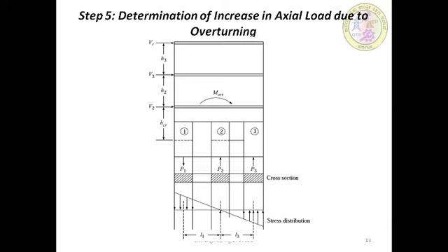Then in addition to these forces, sometimes the lateral forces from winds or earthquakes create a severe overturning on the building. If the overturning moment is great enough, it will overcome the dead weight of the structure and cause tension at the end of the pier wall, which we can see from this figure, how this axial load on the pier is happening because of the overturning action.